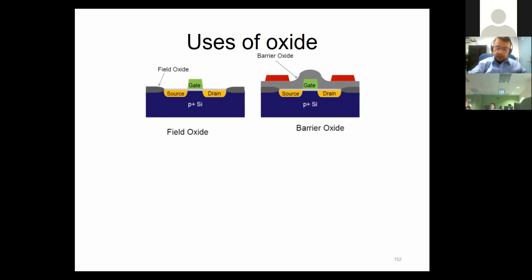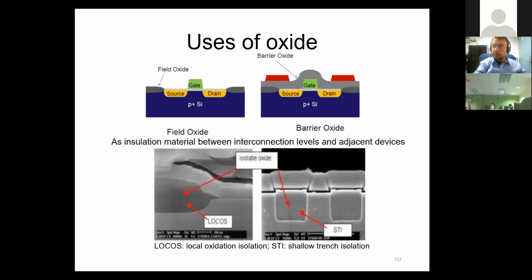And we'd like to also isolate these, let's say, new conductive electrodes that you're trying to create, from the underlying conductive electrode. That's going to be another source of use for the oxide. After all, it's mainly for isolation. That's the main purpose that we're using it for, but there will be a couple of other uses as well. So this is how we isolate and how we create these kind of structures here.